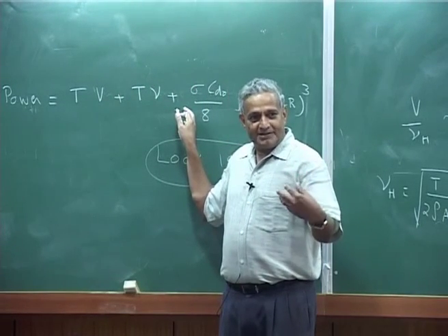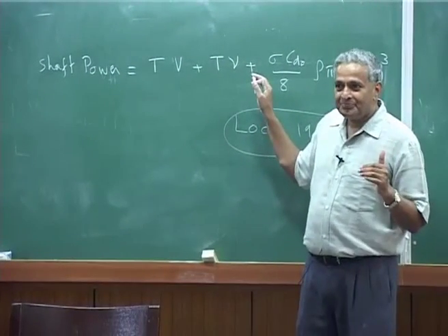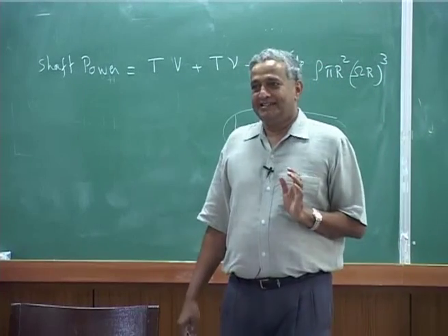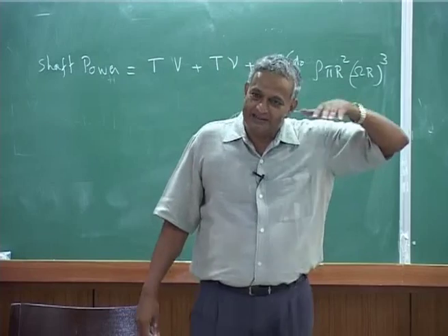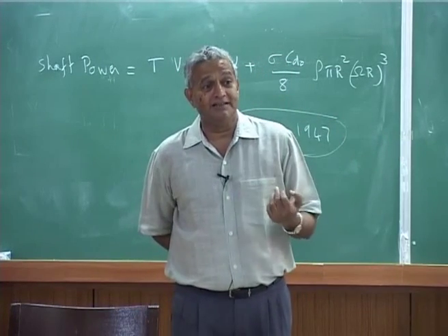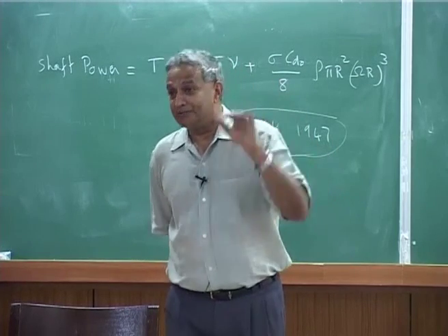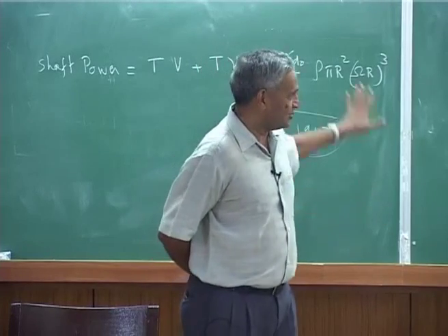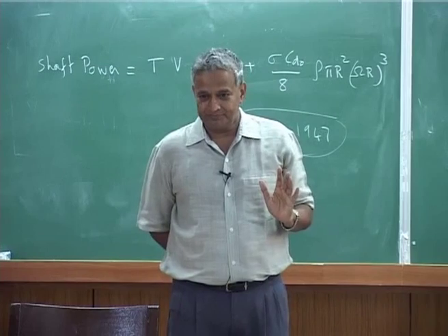Suppose if the power required for a given flight condition is less, then automatically you will also come down with a less speed. That is why you auto rotate at a forward speed where the power required for flight is minimum. Therefore, you auto rotate in that particular speed, okay, because that part comes a little later. Right now, it is only vertical up and down motion.